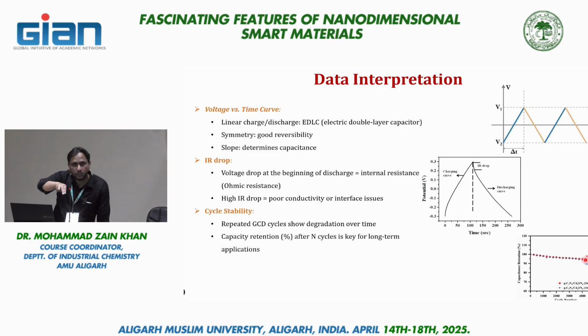Since we are using the two, we got a synergistic effect. The resulting data shows that in our electrodes, because of the presence of these two materials, we have pseudocapacitive as well as EDLC behavior, which means that in our system the charge was stored electrochemically as well as electrostatically. And when we performed the cycling test to evaluate the performance, even after 5,000 cycles, you can see the capacitance retention in these materials.